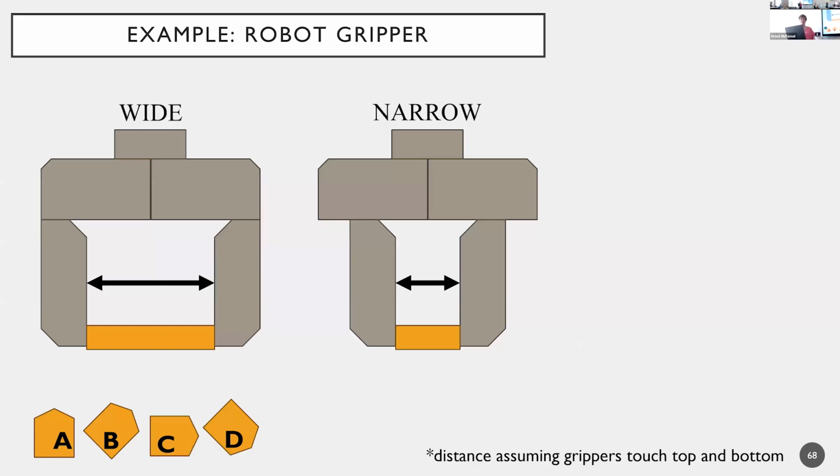So let's consider that we want to examine the impact of augmenting this robot. And we don't want to give it anything fancy. We simply want to know, after it's done squeezing, whether the gripper has closed beyond some threshold or remained open beyond some threshold. And by some threshold, I actually do mean the height of C. So either the gripper has closed and it's pressed down to the width of C, or when it's finished pressing down, it's larger than that, which corresponds to one of these other states.